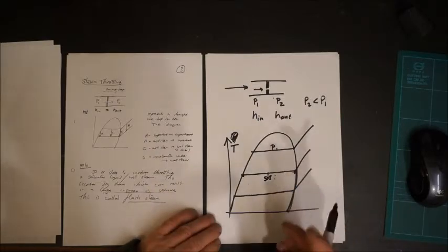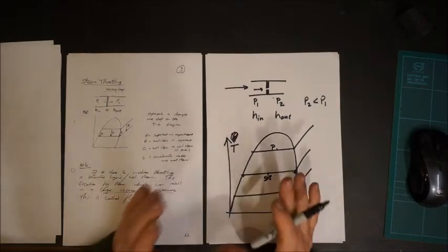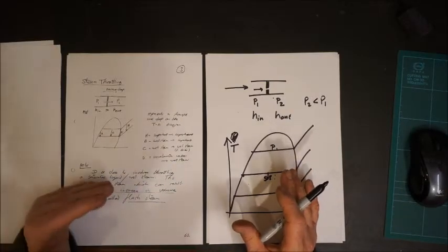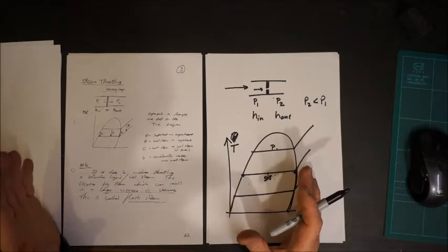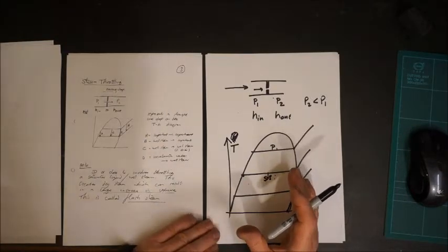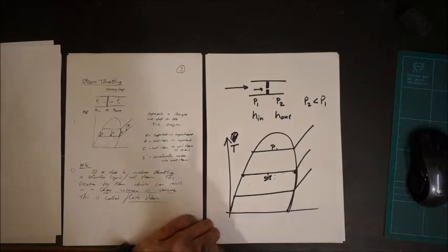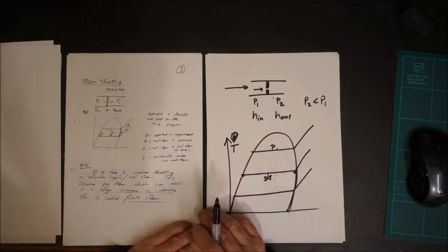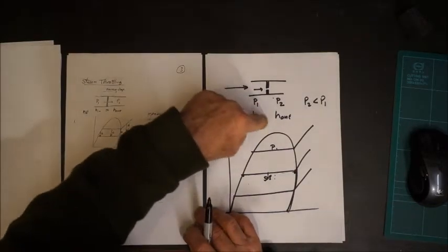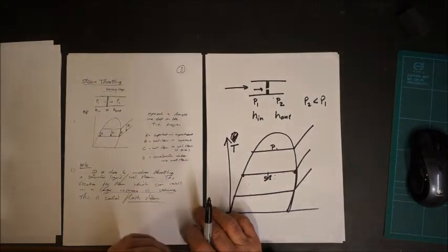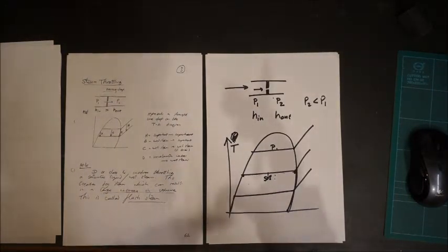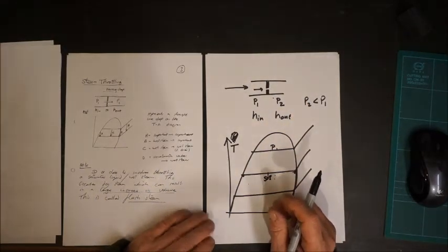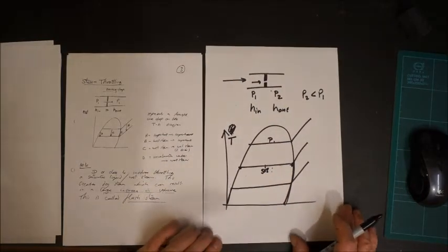Now, no matter how much you try, there's always going to be a bit of moisture in your steam unless you're going for very high temperatures and pressures. So as a result, most steam generation gives you, say, 99% dry. It doesn't give you 100% dry steam. However, you may want to dry the steam, to have dry steam, no liquid water. Or, because the enthalpies are the same and the pressures are different, you may also want to increase the volume of the steam by dropping the pressure. This would be useful if you're trying to drive some kind of machine with it.